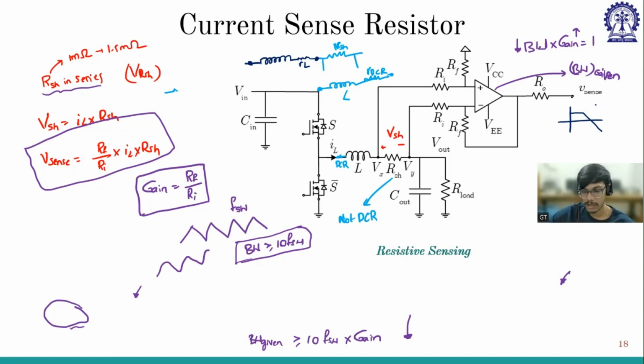It comes from the gain bandwidth product being constant, which is for a first order filter. Sir, if I increase the gain, the magnitude plot will go up, right? Yes, and the effective bandwidth, I'm not talking about the bandwidth of the system, but the bandwidth of the op-amp.